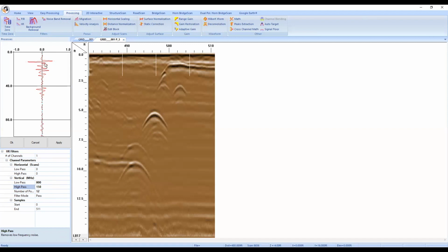And it shifted it a tiny amount, not really by any noticeable degree. 200's messing it up even more. So I think I'm just going to keep it at 100, or maybe 150. Be a little bit more aggressive, but not too aggressive. You can see as we make changes to the high pass filter value that the scan does shift a little bit every time you change this number. You can kind of see how I'm working this. I don't want to go much higher than 200, and you won't notice much of a change when you flip it by like 25 or 50 at a time.